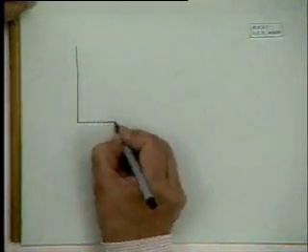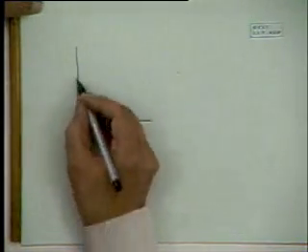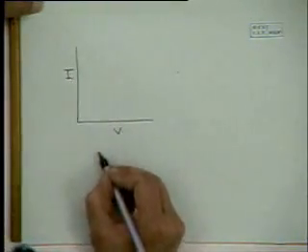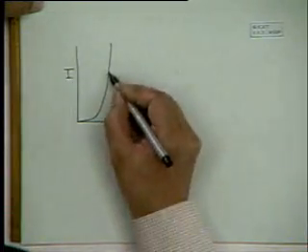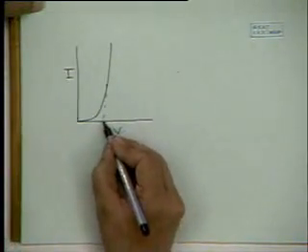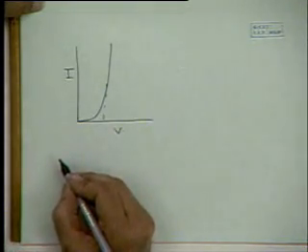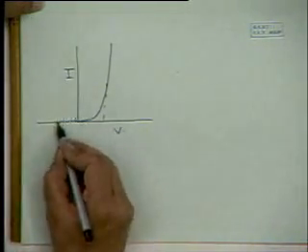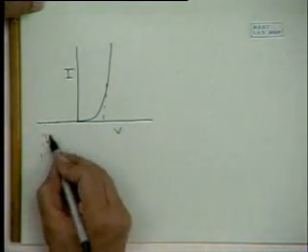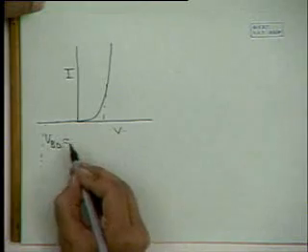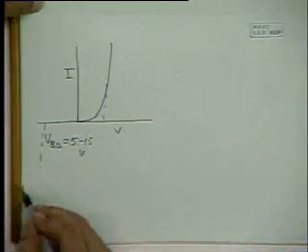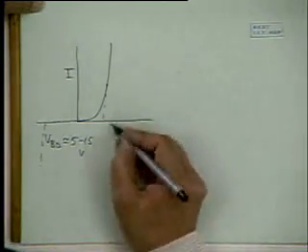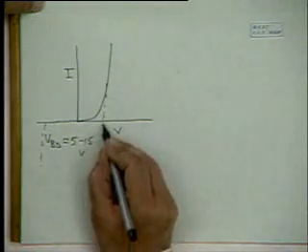These are just PN junction devices, so if you want to characterize them through electrical measurements, you can have the IV characteristic of the device, which will be something like that. The forward cut-in voltage will be an indication of the band gap of the material. In the reverse bias direction, you will get breakdown, and the VBDs are not very high because these are rather heavily doped, so about 5 to 15 volts. So this will also give you an indication of the composition of the material.